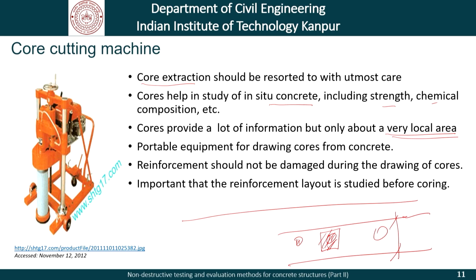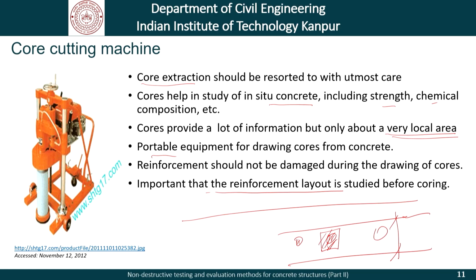We have, of course, portable equipment to help us take cores from different places. We must keep in mind that reinforcement is not damaged during core extraction, and we must study the reinforcement layout, because it is very important to ensure that reinforcing bars are not damaged or cut while the core extraction is carried out. I am leaving it to you to find out more details about what information can actually be extracted from cores which are extracted from the structure and brought to the lab for further testing.